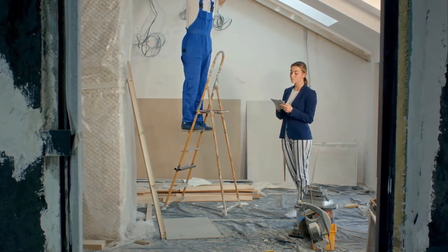If it is more than that, it means there is dampness in the wall. If you apply the wall putty, the moisture will come out and damage the wall putty. So check the moisture level, then apply primer if needed. If there are impurities or surface blemishes, you need to apply a primer if required. This is the surface preparation.